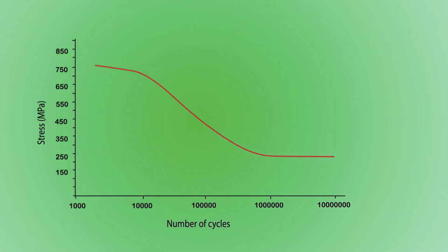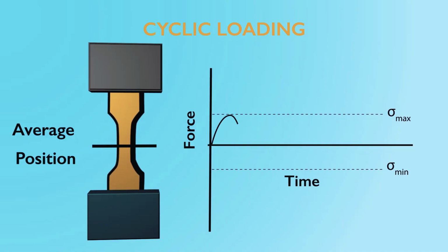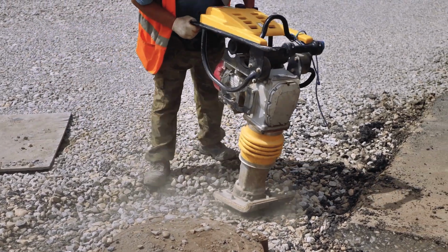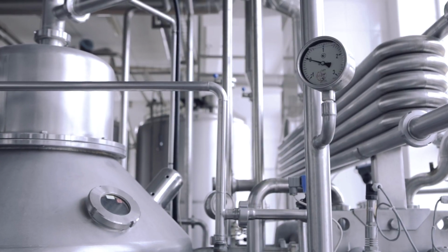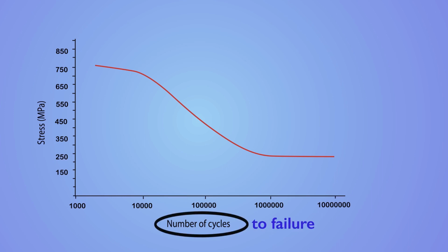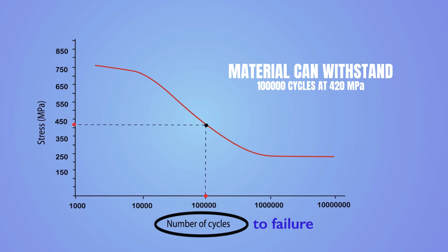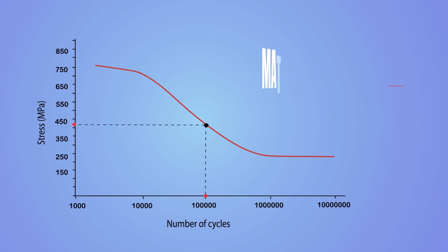Cyclic stress amplitudes refers to the magnitude of the alternating or fluctuating stresses applied repeatedly on a material. This could be due to something like vibration, loading, unloading, temperature changes, etc. The number of cycles to failure means just how it sounds: the number of these stress cycles the material can endure before it breaks or fails.